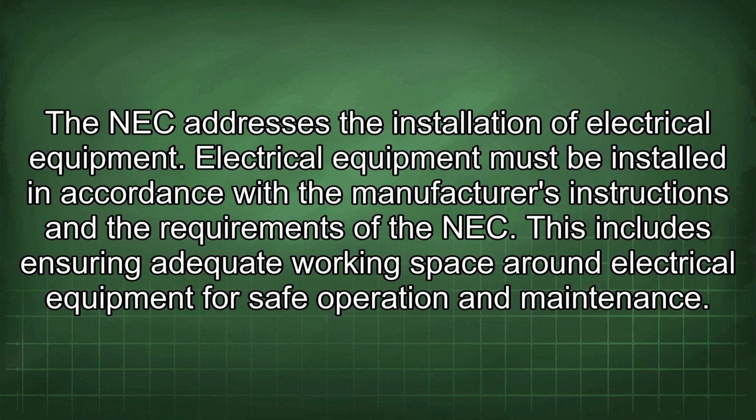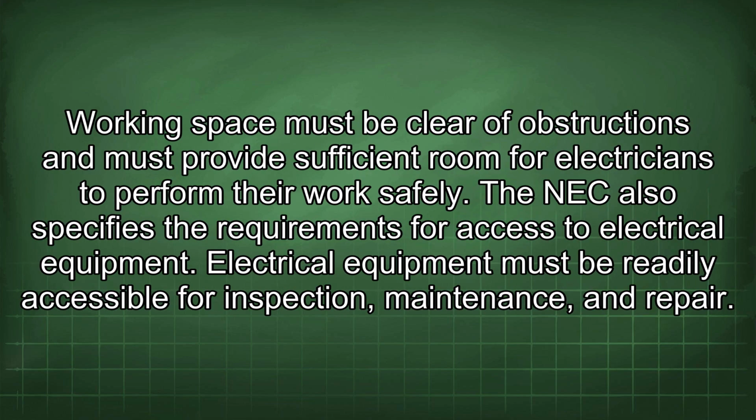The NEC addresses the installation of electrical equipment. Electrical equipment must be installed in accordance with the manufacturer's instructions and the requirements of the NEC. This includes ensuring adequate working space around electrical equipment for safe operation and maintenance. Working space must be clear of obstructions and must provide sufficient room for electricians to perform their work safely.